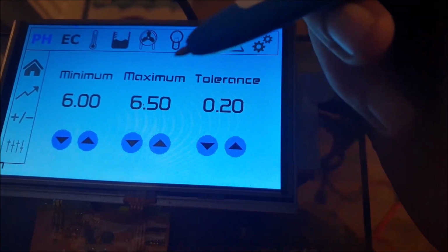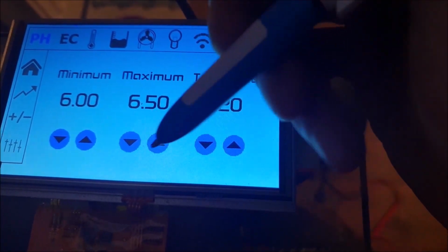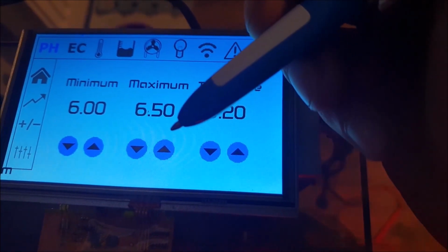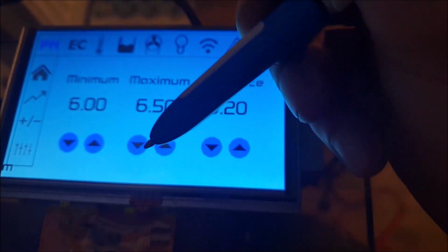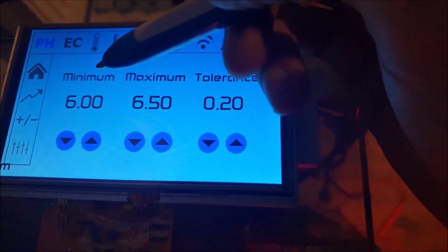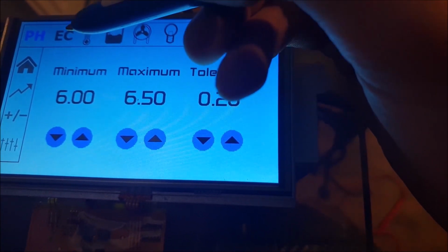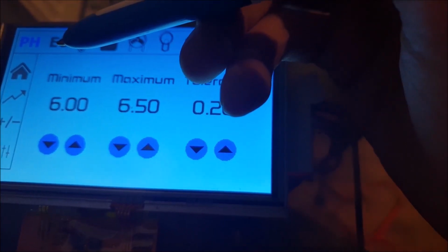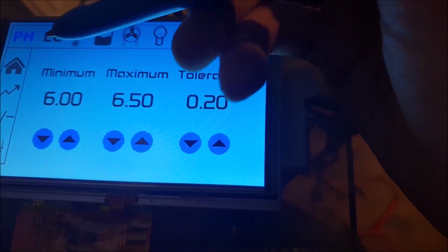Realistically, let's say you're adjusting it every 6 hours, because you want to allow time for it to mix. The longer you have that interval, the better. I can't express that more. Anyway, let's say you have the adjustment interval set to 6 hours. After 3 increments over 18 hours, it's done just the pH, and the EC is still out of range by X amount. It's then going to say, oh well, we've reached our max tries, the EC percentage is greater than 0, let's do the EC this time.